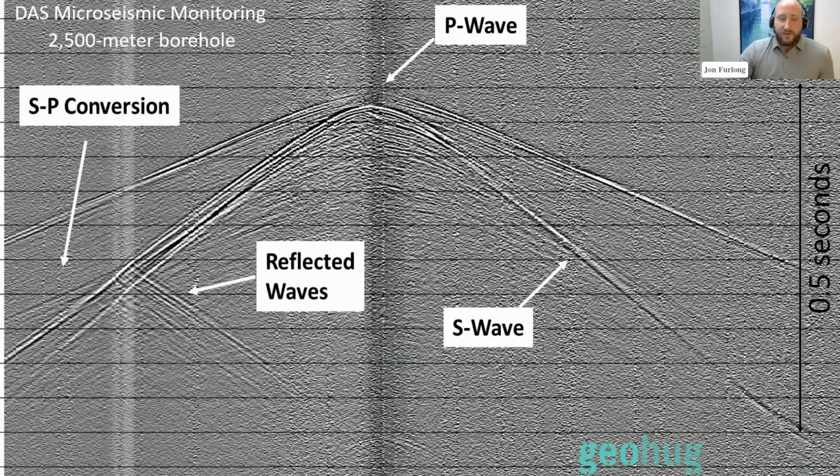So as opposed to a geophone, which does a time residual optimizer by using the P and the S wave arrival to ray trace an event location, here you can use your P wave alone to locate an event, your S wave alone to locate an event, or your P and your S together. So it just adds a lot more resolution to the hypocenter location.